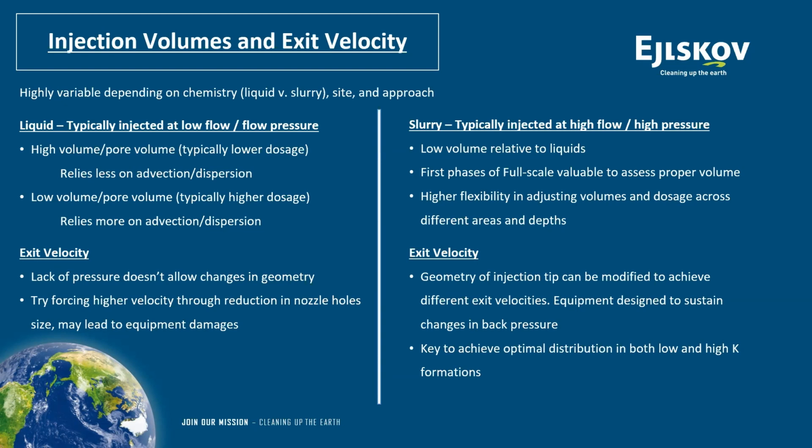And in both, you really want to assess that volume, and that volume may change. Again, your volume may change depending on where you are on site, depending on the geology and the conceptual site model. And so, as that third bullet mentions, you may have to have some flexibility there. And your injection point spacing, just to go back to that previous slide that we just covered, your spacing may change as well.